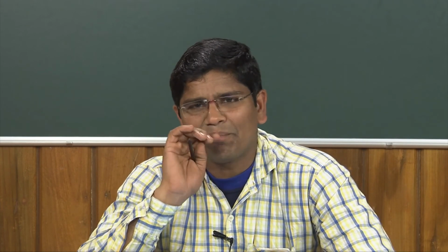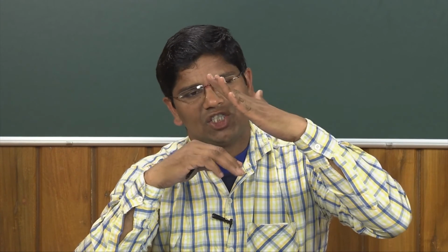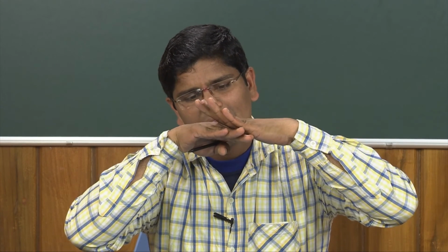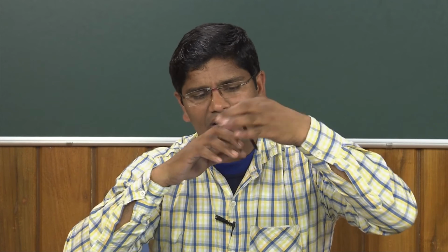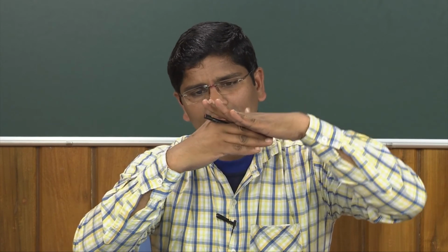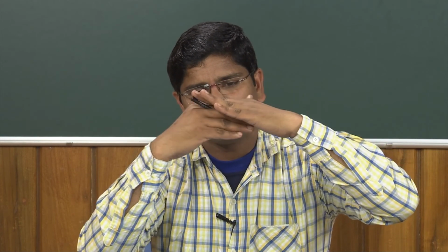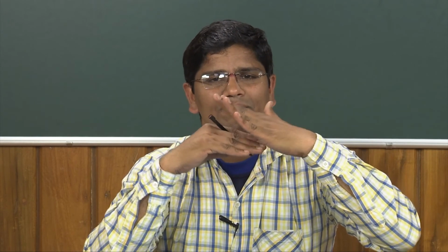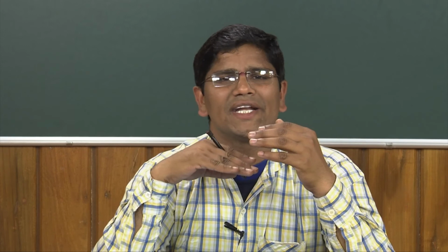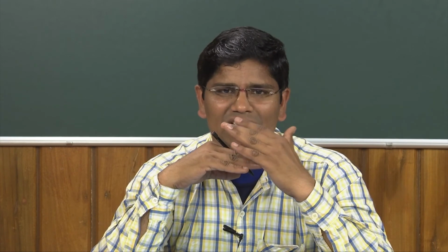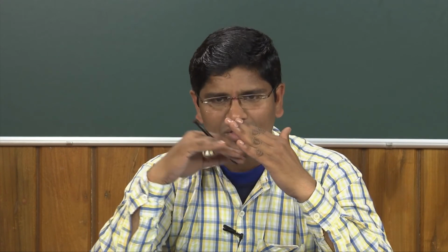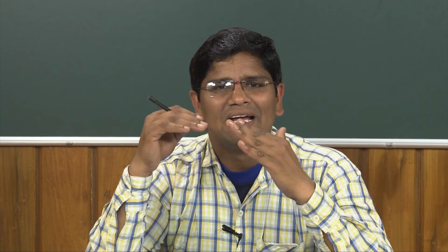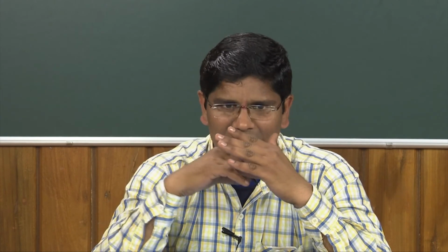Whenever it converts into the vapor, what will happen? It exerts pressure. Assume that I have a chip like this and a cutting tool like this. In between, my fluid jet will come. Okay, this is a fluid jet. If the fluid jet comes, what will happen? Vapor pressure kicks in, but it cannot push down the cutting tool, but it has chances to lift up the chip, so that new cutting fluid can penetrate into the region.